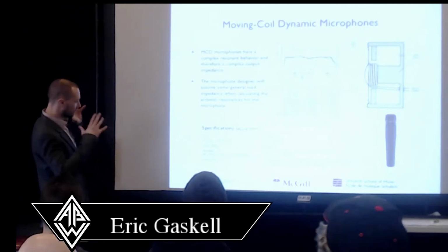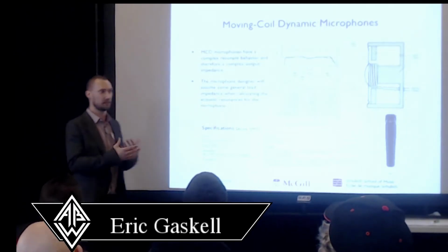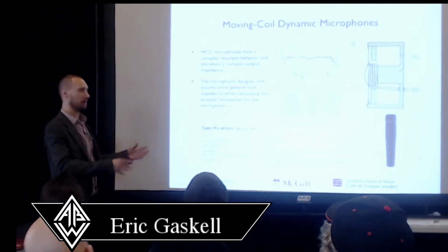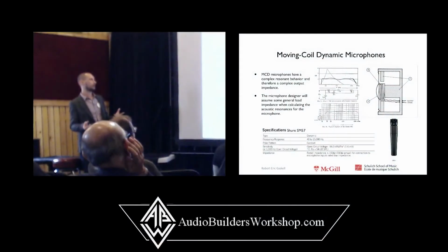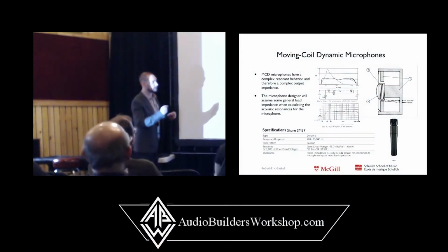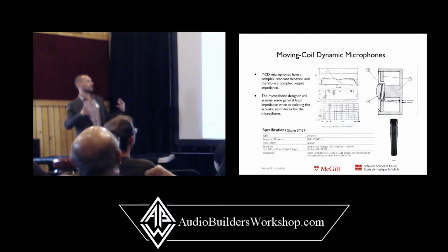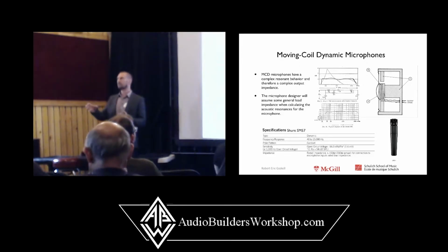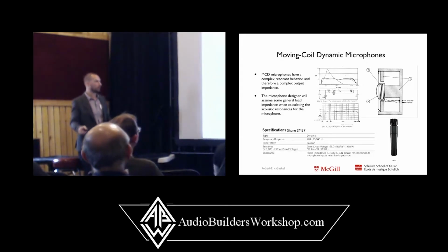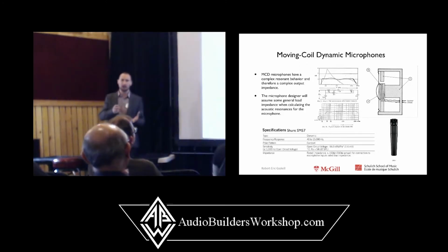This dotted line shows the original frequency response of just the tensioned diaphragm of the microphone. And the goal of the design, as is discussed in this paper, is to create something that extends the frequency response by adding resonances and dampening to that membrane. So there's acoustic resonators, there's mechanical resonances, and there is an electrical transformer at the output.